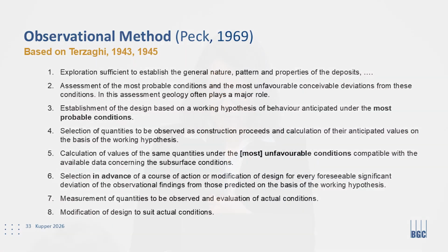You either use the observational method or you do the performance-based design. If you go through this list here, there is nothing here that tells you what method to use. There's nothing here to say use limit equilibrium analysis or use a FLAC analysis, a deformation analysis. This is simply an approach to manage variability, uncertainty, and risk.